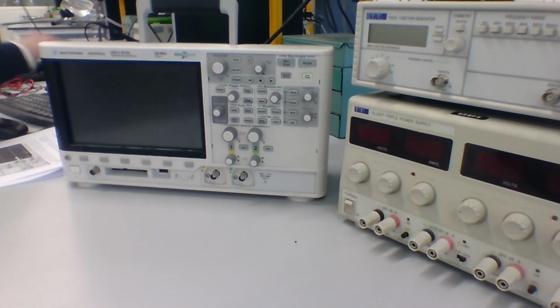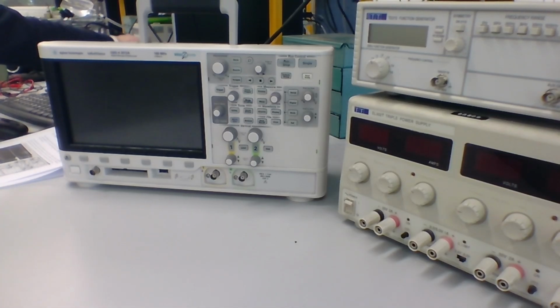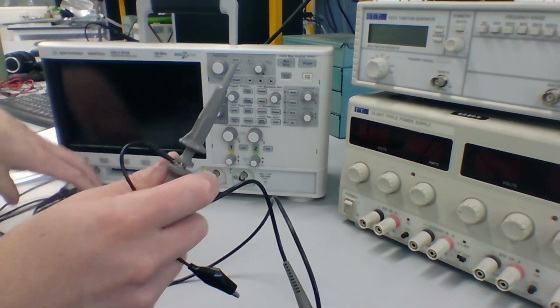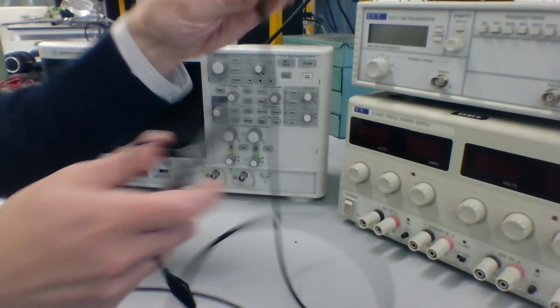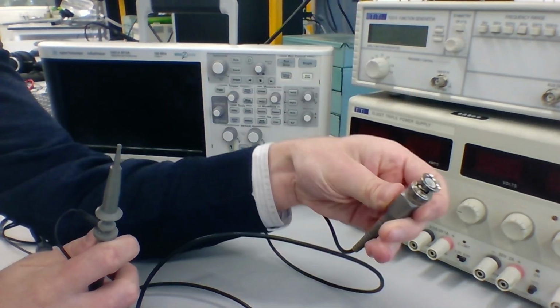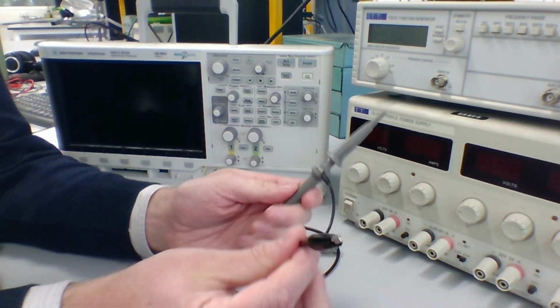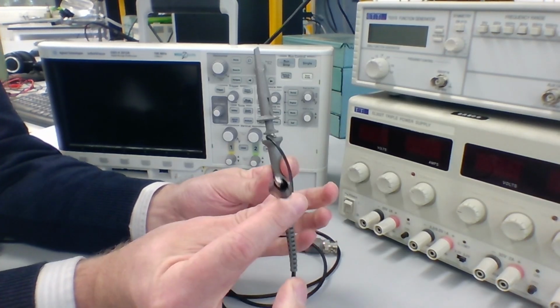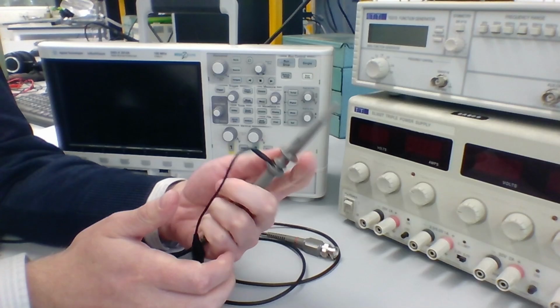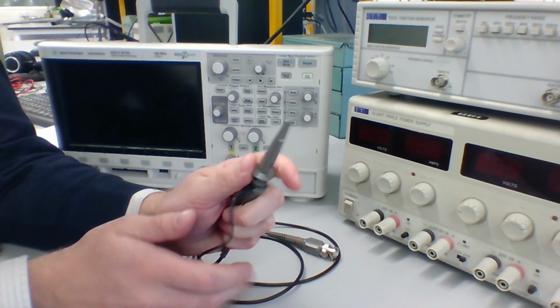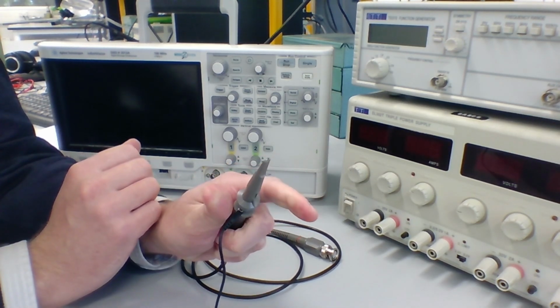What we're going to need, first of all, are our oscilloscope probes. And these look like this here. They have on one end what's called a BNC connection, looks like this. On the other end, they will tend to have a double connection that looks like this: an alligator clip, which we use for our ground reference, and a shielded hook tip. This, we pull it back, there's a little spring inside here to protect this hook so it doesn't get damaged.